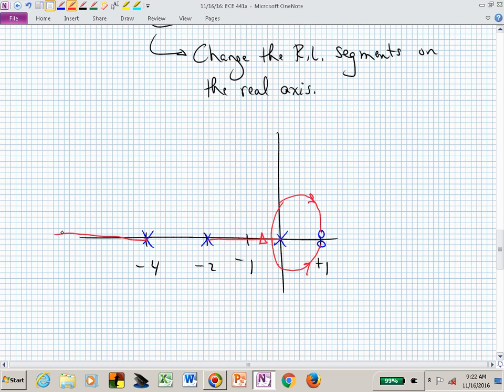You know you have another pole over here, but where's your third pole in this root locus? If I've picked the gain to be at minus 1/2, I think the breakaway would actually be a little to the left of minus 1/2. But just to think about, what if the breakaway was to the right of minus 1/2? Where would the third pole be located?